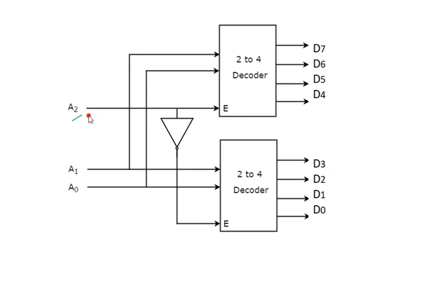A2 is the extra variable, that is nothing but the enable value. Consider this is 1, so 1 is directly given here. But here I have taken a NOT gate, so I am taking 1 here and it is 0 there. So A2 is given directly to the first decoder circuit, and the inverted A2 is given to the second decoder circuit because of this NOT gate, and these are my outputs. This is the block diagram of the 2 to 4 decoder circuits.